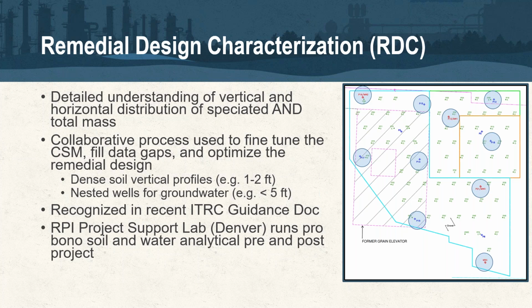If we've got a long groundwater screen, like a 20-foot saturated screen, maybe we're doing some nested implants, or we're grabbing some temporary groundwater samples as well. This RDC process was recognized in the recent ITRC guidance document. If you'd like a link for that, please let me know, or you can just go to the ITRC website. I'm sure it's easy to find.